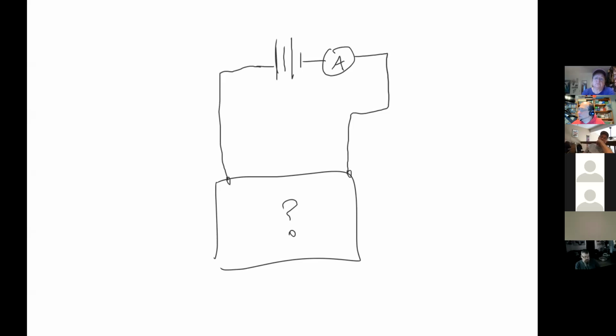We measure by using Ohm's law, E equals I times R, so R is equal to E divided by I. Let's say our resistance is initially really, really low, which means we have tons of current flow, and then the current flow goes all the way to 0.